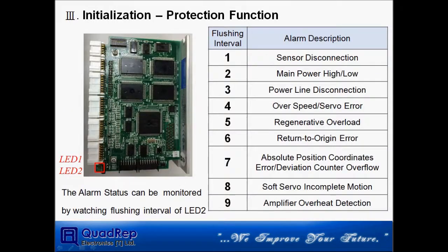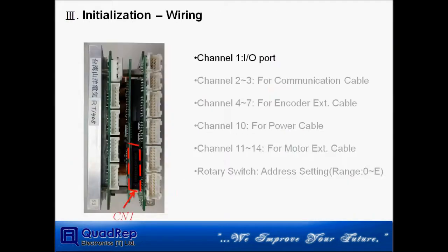Our driver has protection functions. LED 1 lets us know if our driver is turned on or not. And the alarm status can be monitored by watching the flash interval of LED 2. And the meaning of each alarm is shown in the table.